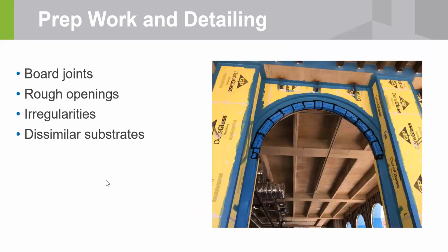So here are more pictures of the installation. All the openings were back wrapped either with an embedded reinforced liquid flashing or with a peel and stick. And so for the fenestration, there's going to be a silicone perimeter sealant that seals the frame of that unit to the air barrier that's back wrapped into the rough opening. So that's where the seal is going to occur.